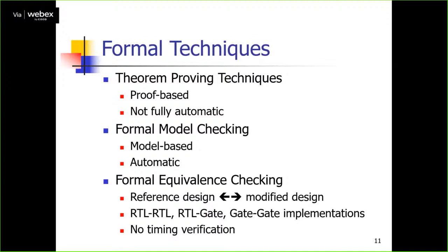So the last one is a very important one, where you make sure of a more comparative analysis with respect to a reference design and a modified design. That type of analysis is called equivalence checking.